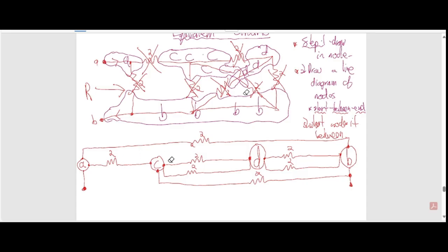Alright, so basically we're kind of done. But what this has allowed you to do is it's way easier to see what's in parallel and what's in series. I don't know if you realize. You could clearly see the things that are in parallel, and you could clearly see how this whole circuit boils down. So my first question to all three of you, and I want everybody to answer: everybody's seeing that between C and D, those two resistors are in parallel. Everybody's seeing that, right?